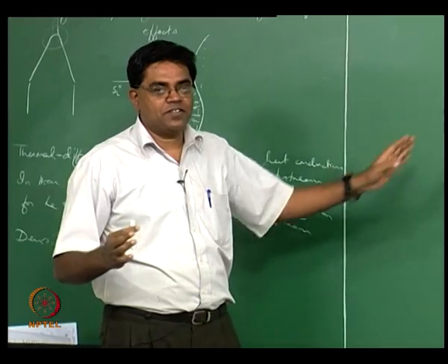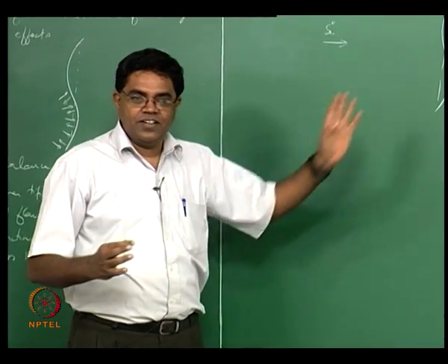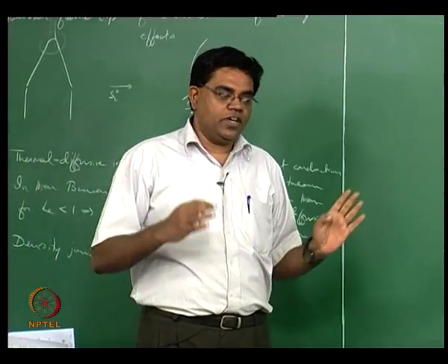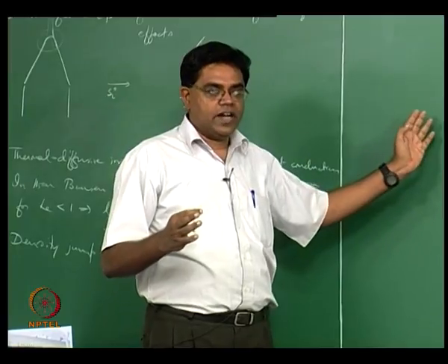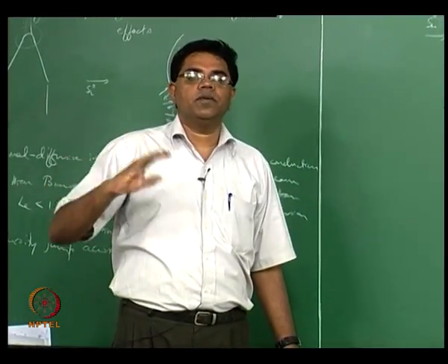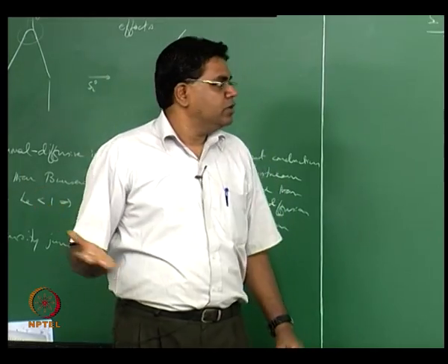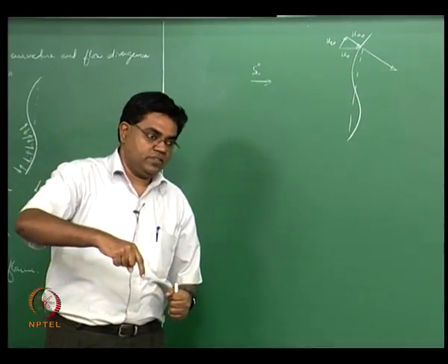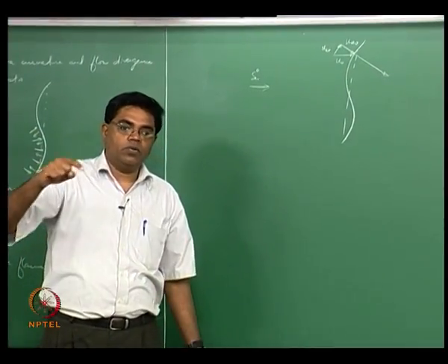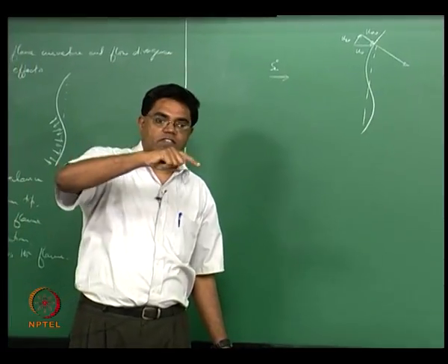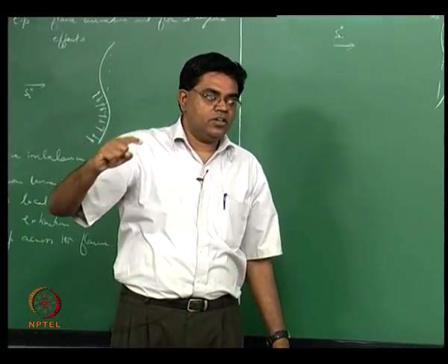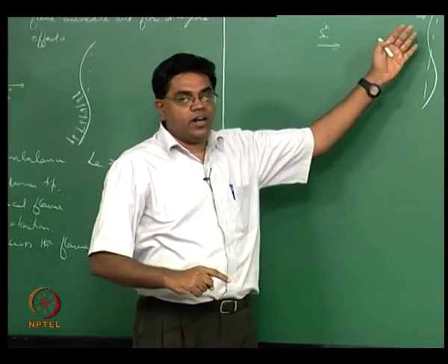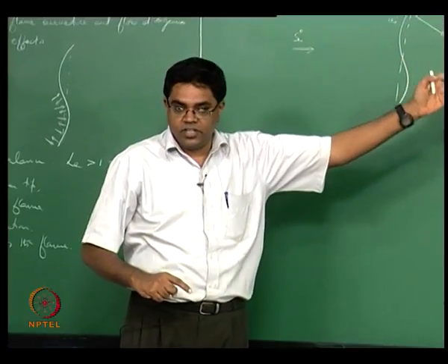Okay, think in terms of factors of 3 or 300 for the sake of simplicity, or 3000. So you're now talking about a factor that's somewhere between 7 to 10 times more. So this has to be significant, and the density correspondingly decreases. So P equals rho RT, and as T increases rho has to decrease, and then rho naught U naught is equal to rho infinity U infinity, or more specifically in this case rho naught Un naught should be equal to rho infinity Un infinity.